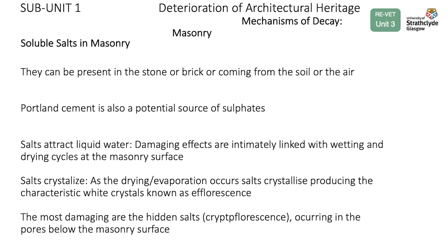Soluble salts in masonry can be present in the stone or brick, or come from the soil or the air. Portland cement is also a potential source of sulfates. Salts attack with liquid water. Damaging effects are intimately linked with wetting and drying cycles at the masonry surface.